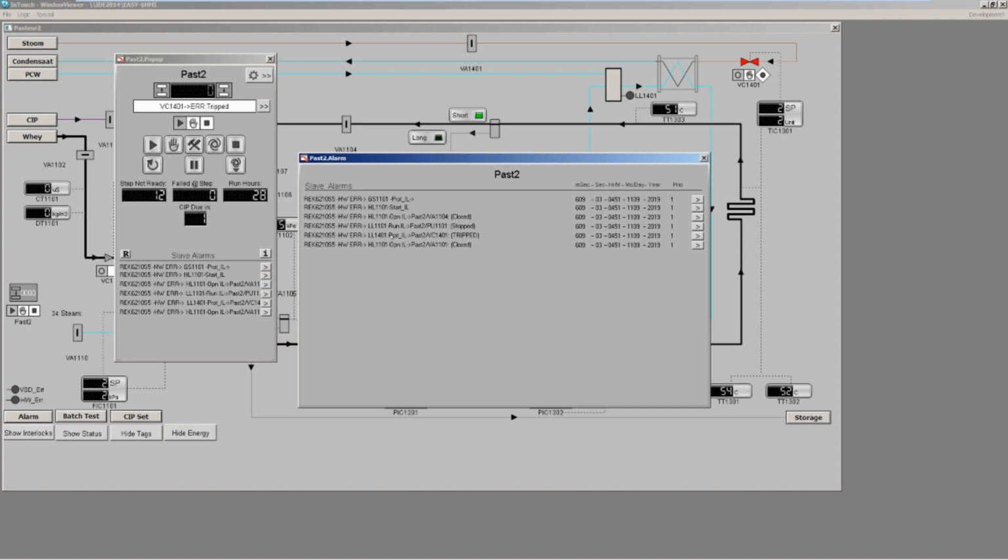It affects the low level switch 1401, which is used as a protection interlock to the S88 path, the affected device, and the state of the device. With one view, the operator sees the extent of the problem and the integrity of his system. The operator is very much empowered by this information. Not only does the operator see with one view the extent of the problem, but also what devices are affected, and more importantly, how these devices are affected.